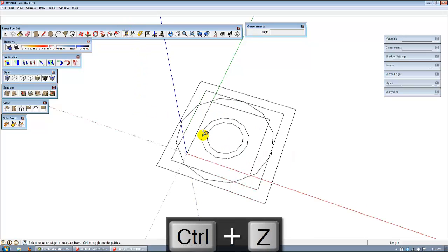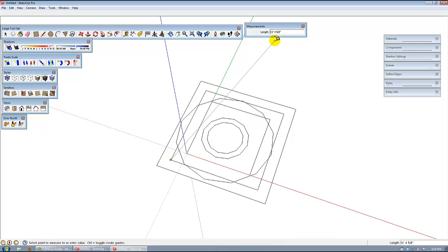The tape measure tool. We can grab the tape and measure 17'6" up here. You can see up here you get different numbers, different measurements. Once again, there's a Control function for this. If I click Control on the keyboard and then click not on a point, but on any sort of line, and then drag it out in the middle of any line, I can create a guideline.